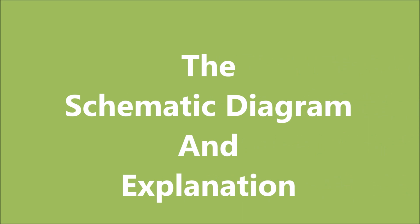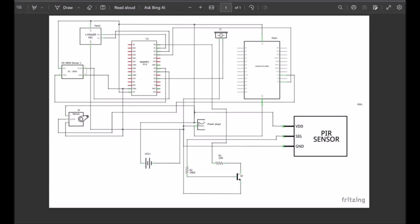Let us begin with the circuit diagram of the project design. The schematic diagram shown above is designed around two development boards. The NodeMCU was used to send the sensor readings to the IoT Blynk server through a Wi-Fi connection that has internet access, while the Arduino Pro Mini board was used to control the actuators like the servo motor.